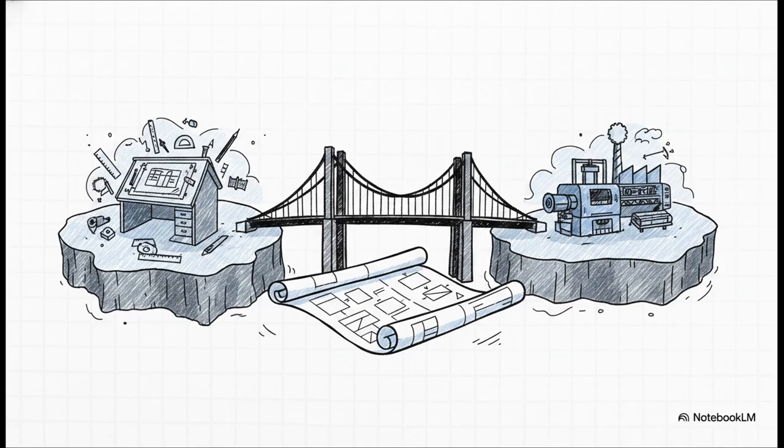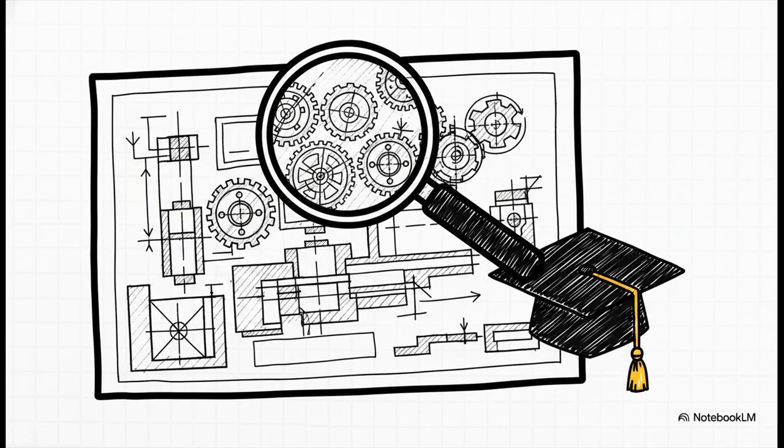And always ask yourself 3 things. Is this tolerance feasible to actually machine? Is it realistically measurable by the quality team? And is it truly functionally necessary for the final assembly? You now have the professional framework to confidently interpret complex production prints.